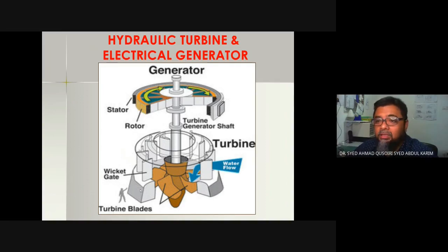So they have an entire massive room for water to come in and spin the blades. And here we have the wicket gate, like a valve. They are going to close it when that turbine is not in use. It means diverting the water flow so that it doesn't hit the turbine blades. So the water will spin the blade, the blade will rotate the shaft, the shaft will rotate the alternator. Inside this, of course, we have copper cables and magnets. This is how electricity is generated.